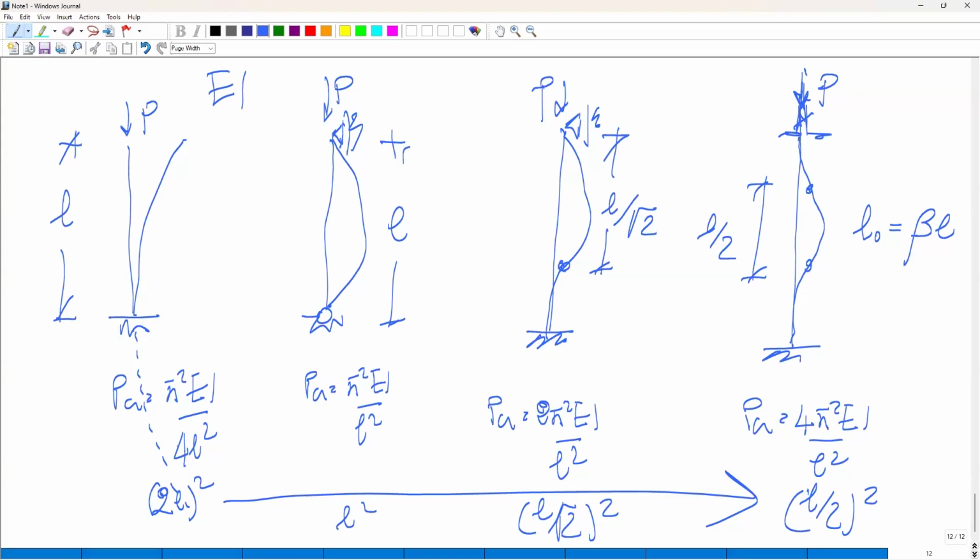Well, E, you can act on E, but we have seen yesterday, when we doubled the strength of concrete, our stiffness increased by 20%. But doubling the strength of concrete is not just increasing the stiffness, and so the critical load, by 20%. 120 megapascal concrete, as we have seen yesterday, is not only 20% more expensive than a regular concrete. It can be 2-3 times more.